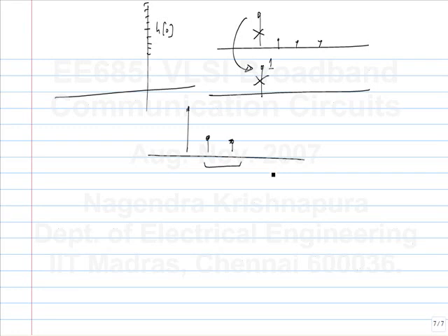Now in presence of noise, this turns out to be the optimum. We'll see later exactly how it comes out. No, it's not, because why is it the same as crosstalk? White noise is not crosstalk. The main difference is, when we think of simultaneous channels, what happens for one channel happens for the other channel. So if you amplify the signal in some way, the crosstalk channel also gets amplified in the same way. That is not true for white noise.